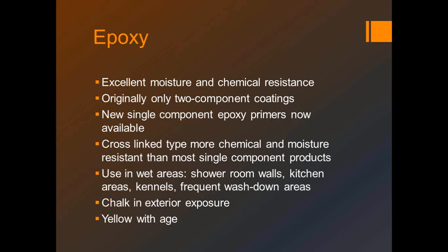to the floor, letting it dwell there for 24 hours, pulling the plastic up, checking is it darker underneath the plastic than it was around the surrounding floor. If we do have darkness underneath there, we probably need to actually get into the calcium chloride checks just to find out how much moisture we got in that slab. The last thing you want to have happen is to do an epoxy floor finish on a slab and then 3 or 4 months later end up going in taking up great big sheets of the stuff because you had moisture in that slab that was unaccounted for.